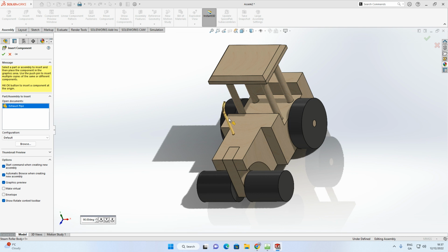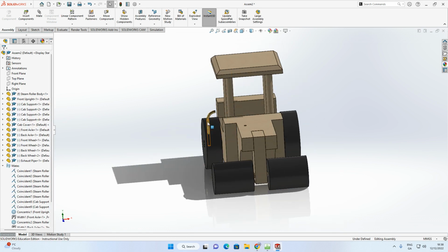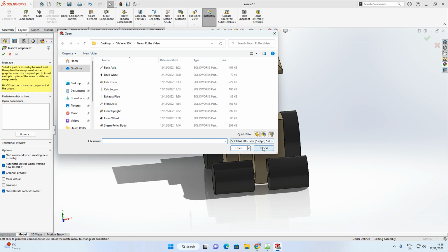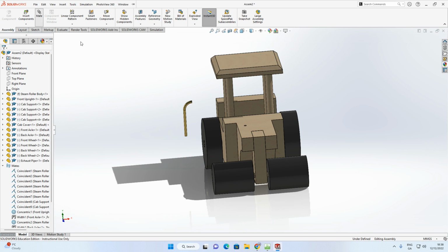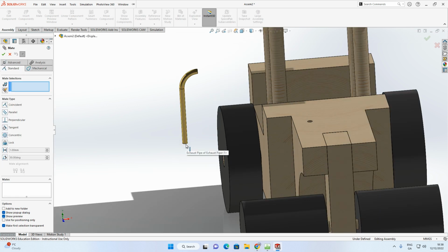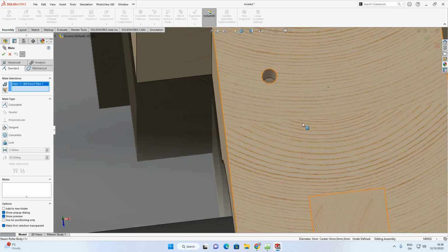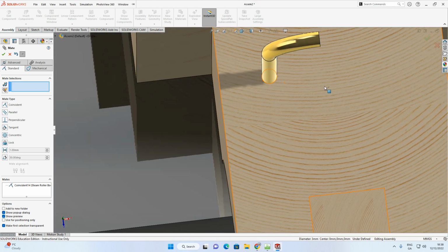But the reason I'm going to get you to do something here now is because we're going to mate with planes. So I'm actually going to leave it this way. As I said, the easiest thing to do, no one would notice any difference if you just mated it that way. But we're going to have to stick with a reference, so I'll show you now. I'm going to leave it that way. So, accept. Now, first thing we'll do is mate, apologies. Select the bottom circumference and then the inside circumference in there. There we go. Now it's gone in.